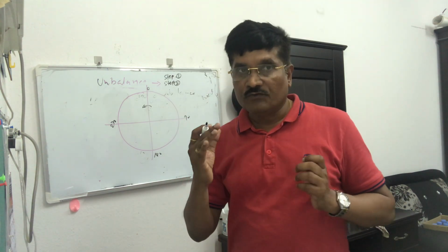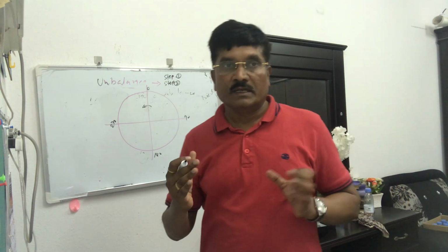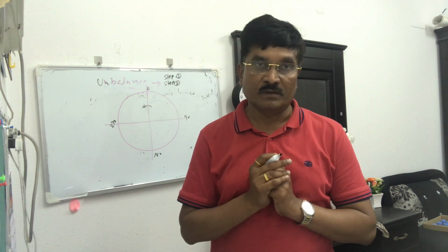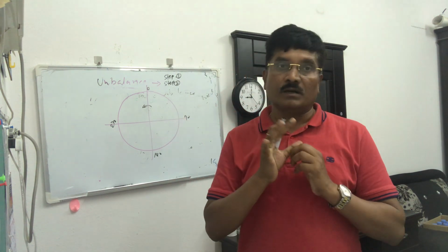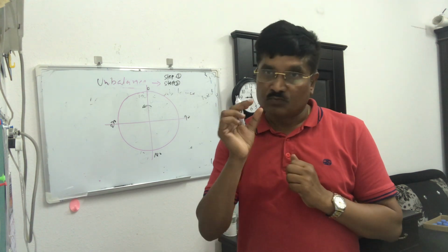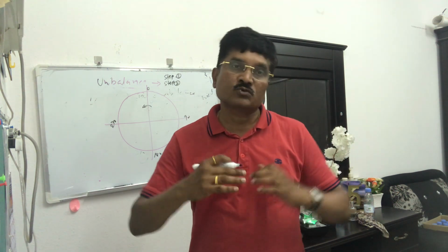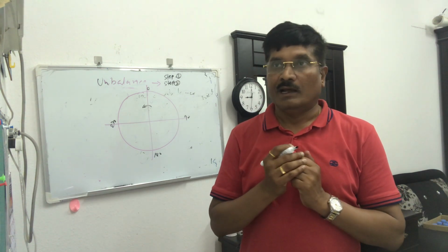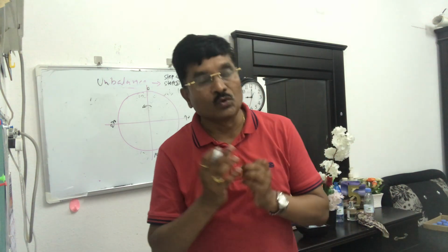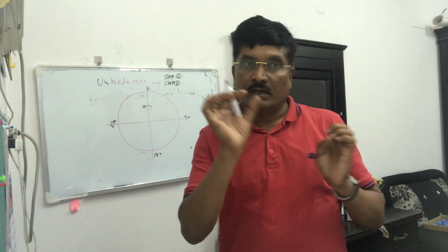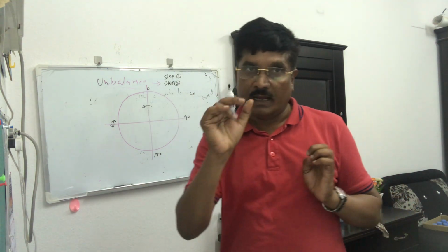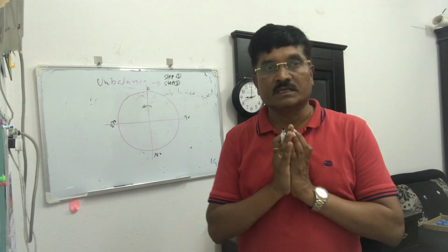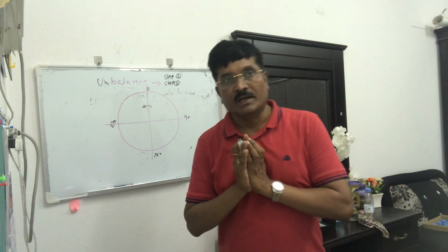Means if you increase the speed by 2 times, then vibration force increases 4 times. So be alert about the speed. A small weight also magnifies vibration too much at high speed. Keep that in mind. Another thing, the unit of unbalance is gram mass multiplied by the radius from the center line, gram mm. This is the unit of the unbalance.